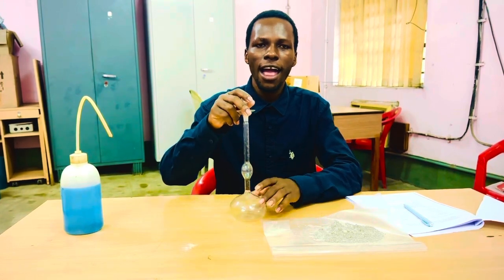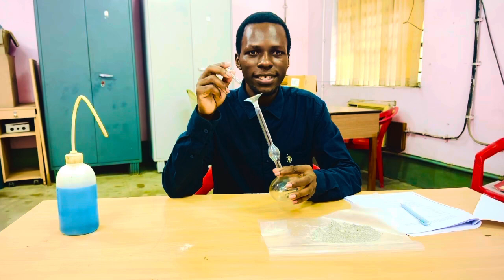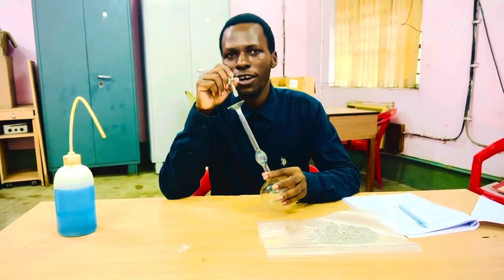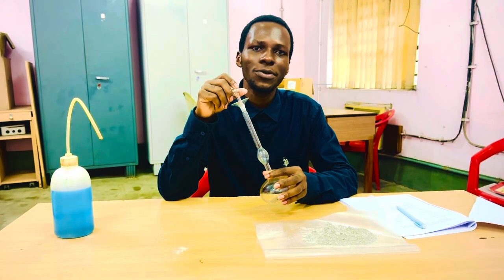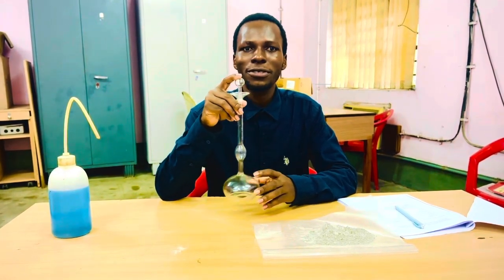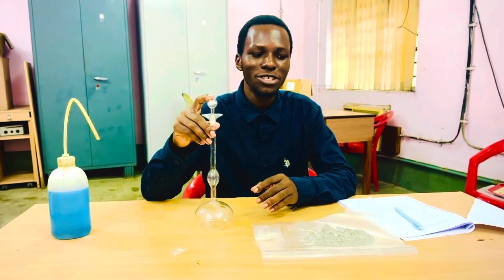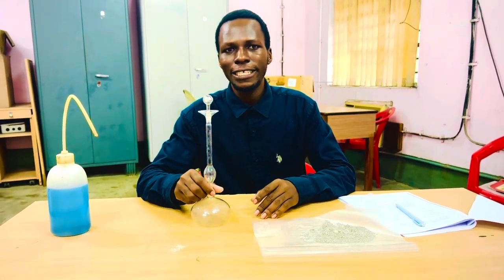With me here, I have what we call the Chatelier flask. With this flask, we can get the density of cement, which, if you remove the units, gives us the specific gravity of cement. For instance, when you go to a construction site and need to do the mix design, you need the specific gravity of cement. If you have this flask, it is quite easy to do.